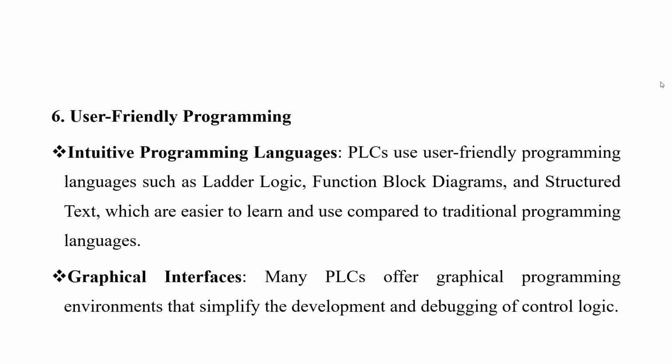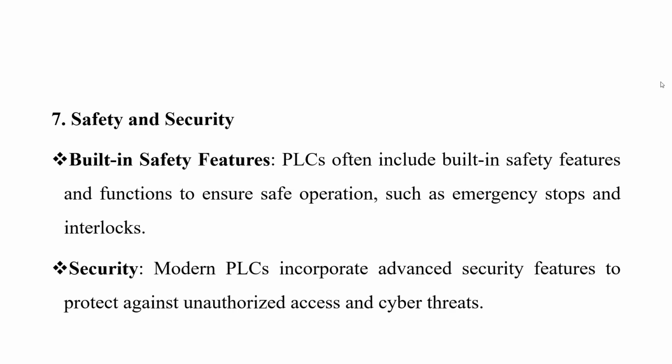They also use a user-friendly programming mechanism where you can use ladder logic. You can use function block diagrams. You can use structured text, and these are easy to learn and use. When you compare ladder logic, function block diagrams, instruction list, structured text, with the traditional programming of microcontrollers like studying C, C++, assembly language, you find it is a little bit more friendly and easier to learn than those other programming languages for microcontrollers. Then, because of the graphical interfaces, you are able to also see what you're programming, and this is easy because of graphical programming environments.